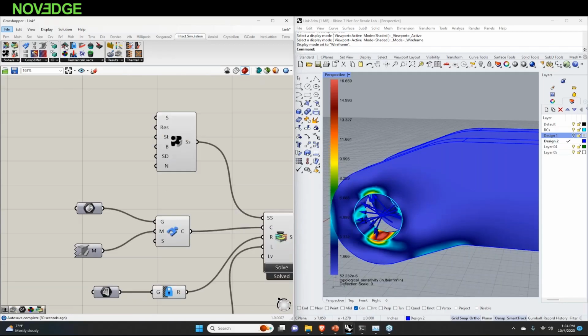So here we've got the bearing loads. I showed bearing loads, restraints. Here's the linear acceleration load option, rotational load option, a vector load, displacement boundary conditions, where we can specify how particular faces are displaced in particular directions, whether it's 0 or a particular specific displacement amount. There's a gravity load. We also have pressure loads and torque loads.